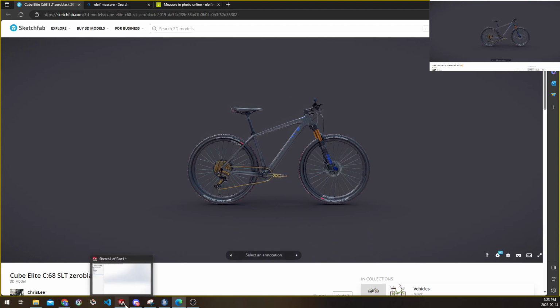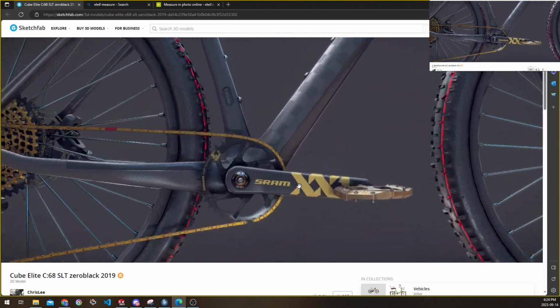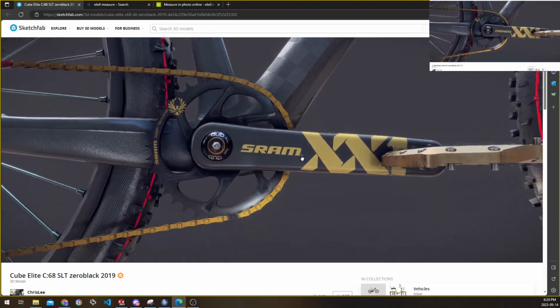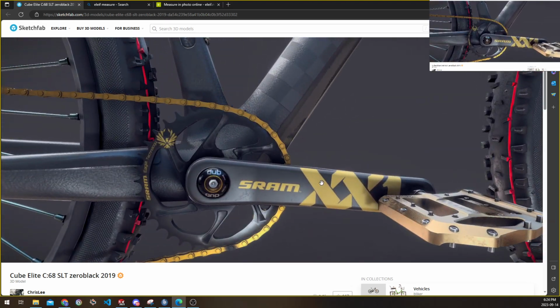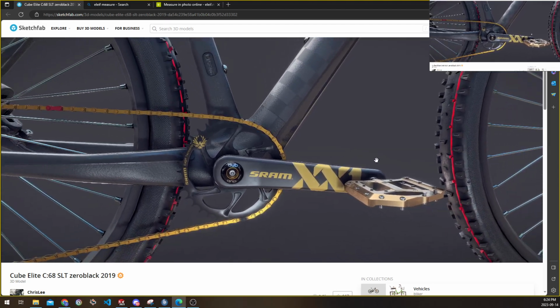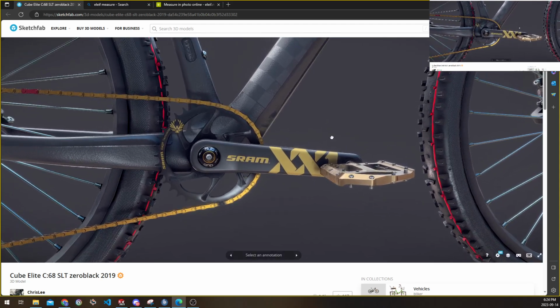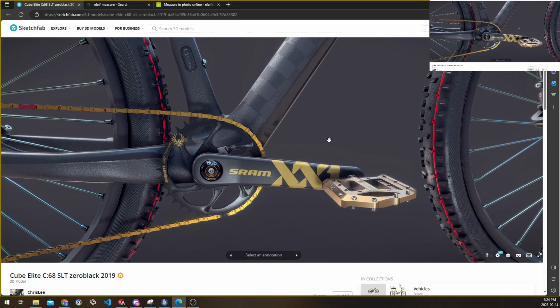Oh, I have a quick question. Yeah. For the pedal, right? The sprocket, the shaft, and the pedal. If you made it all in one, would the origin change, or would it only be in the middle of the shaft? So it depends on how you define it. If you did it as a sub-assembly, then it would likely be the origin at the center of whichever part you made the assembly with first.